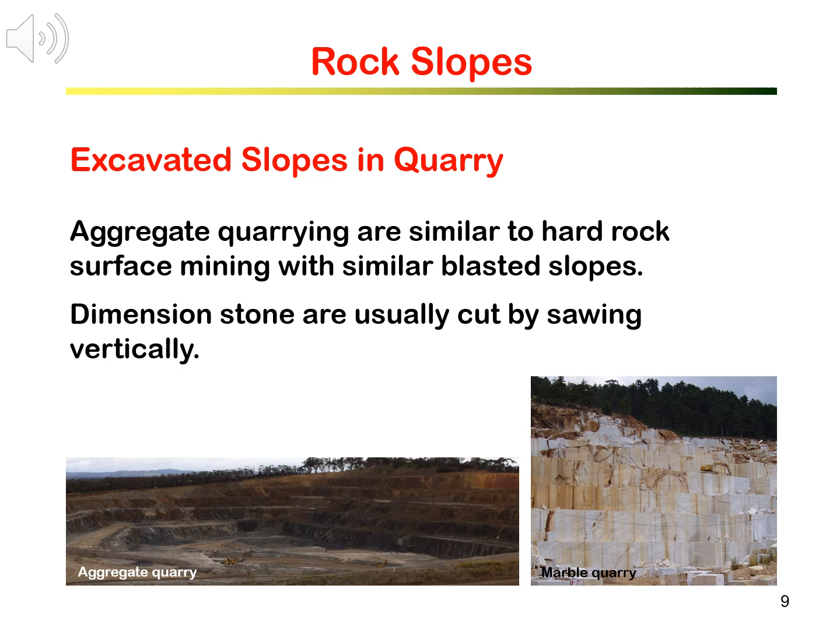However, it may suffer from rock block and wedge sliding when the joints are oriented unfavorably. We will learn a lot more on block and wedge sliding on unfavorable joint orientation later when we learn slope stability analysis and the failure modes.